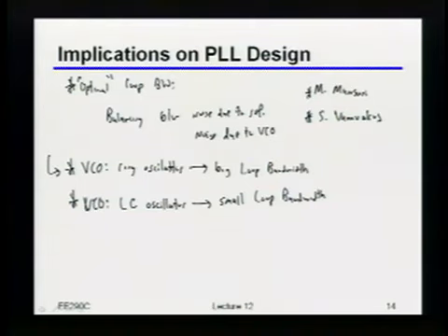Yeah, when you mean as high as you can, do you mean with respect to settling time constraint or? No, stability, because remember, there's only so high I can make it given my reference frequency. Right, by 10, exactly that, by 10 or by 5 or whatever it is. If you guys are interested, there are some tricks where you can mix between a DLL and a PLL and get even farther than that. But bottom line, you try to make it as high as you can.